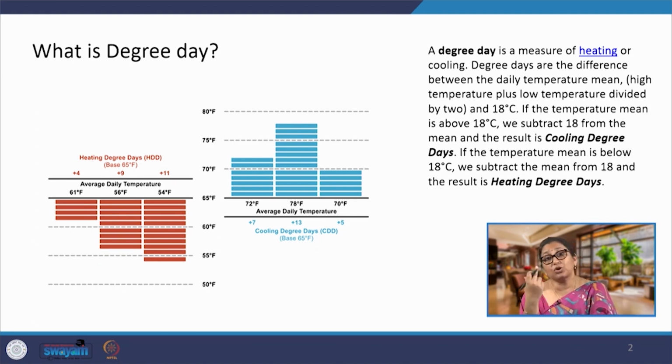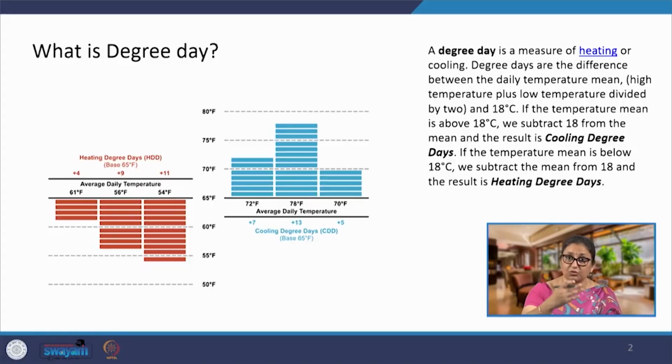If we are taking it on an hourly basis and then converting it, then we would know that for 1 hour the temperature remains 28. So, 28 minus 18, 10 degrees centigrade for 1 hour. That is only degree-hours in an hour. If it remains that for 24 hours, we can divide it by 24 hours to get the heating degree day or cooling degree day. Similarly, we will do the same thing for all the places.